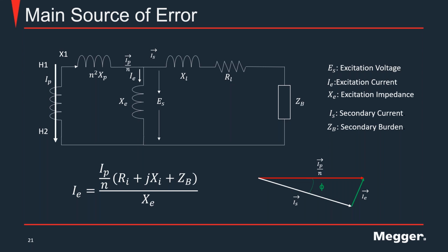One thing that comes up quite a bit with metering CTs is that people are mostly interested in the ratio and polarity. If you truly want to find out the accuracy class of the CT and how accurate it really is, you need to run what is called the ratio error test, in which you generate the ratio error tables. And in order to generate the ratio error tables, you also need to run the saturation curve.